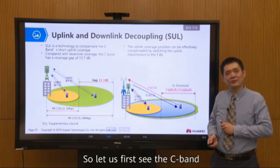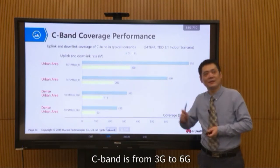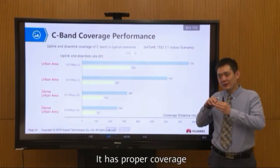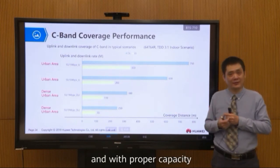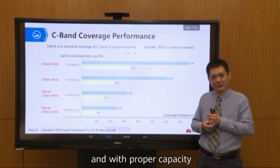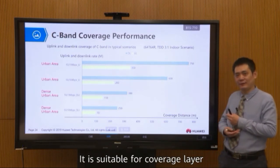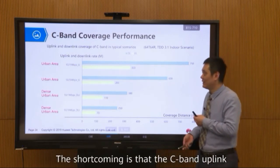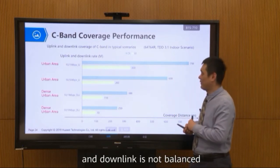So let us first see the C-band. C-band is from 3 gigahertz to 6 gigahertz. It has proper coverage with proper capacity, and it's suitable as the coverage layer for 5G. But it has a shortcoming. The shortcoming is that the C-band uplink and downlink are not balanced.